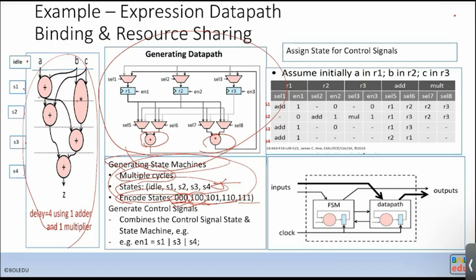For each pipeline stage, when you draw the line, you see how many states will cross the pipeline stage. The maximum is 3 crossing points, so you will have a 3-state register. So you have 3 state registers and 2 operators.